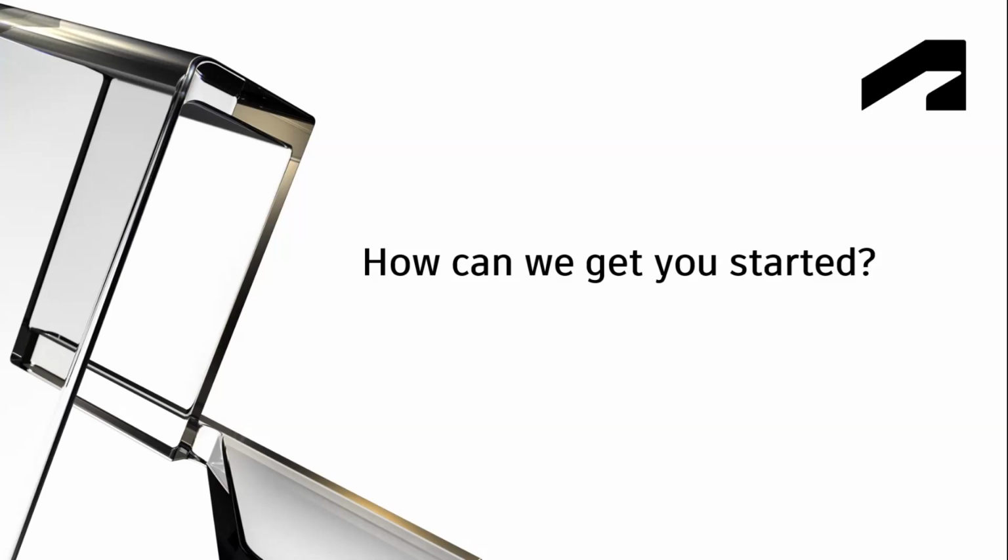Yeah, I'm here. Thanks, Syed, for the quick overview and short presentation of the Nastran In-CAD capability. Once again, the good thing about Nastran In-CAD is that whatever material is assigned in the modeling is automatically brought over to Nastran In-CAD. But as Syed showcased, should you want to change any of the material, you can still override the material property from aluminum to steel or steel to concrete, and so on and so forth.